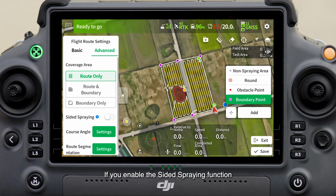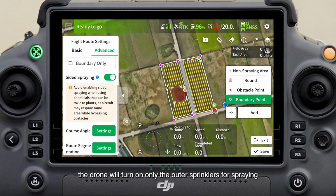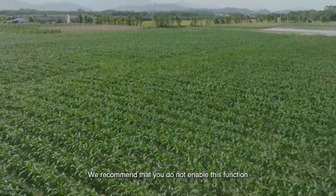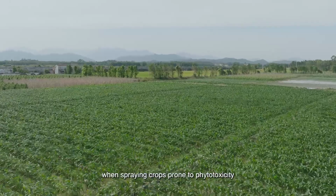If you enable the sighted spraying function, the drone will turn on only the outer sprinklers for spraying during lateral movement or turn on only the inner sprinklers during bypassing. Take note that there is a risk of overspraying when this function is enabled during bypassing. We recommend that you do not enable this function when spraying crops prone to phytotoxicity.